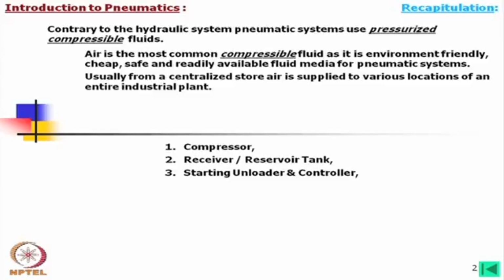Now, that we need to release before starting the compressor again. For that, the system which we have discussed earlier is called a starting unloader, and also there is a controller. If we need better control nowadays, an electronic control system, maybe with the hydraulic circuit, can be utilized for that.